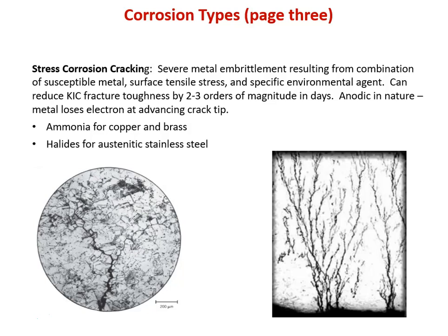So stress corrosion cracking is a condition under which the material's K1C will drop as a result of its exposure to a corrosive environment and its own tendency to corrode. There are a lot of different actual mechanisms by which this happens. Film breaking at a crack tip of a passive material, absorption of aggressive species at a crack tip. These are all going on at the atomistic level. Won't go into them, but the important thing to remember is you need a susceptible material, a pre-existing tensile stress, and the unique environment that makes it susceptible.